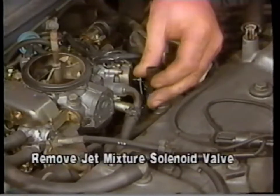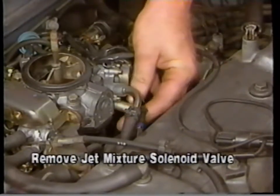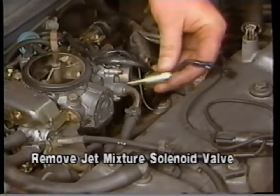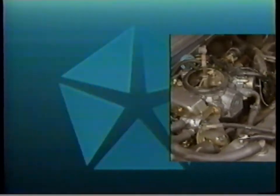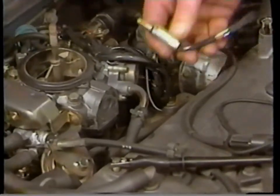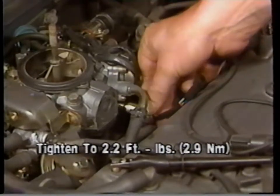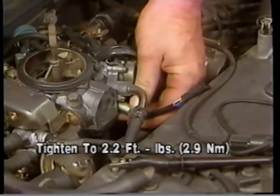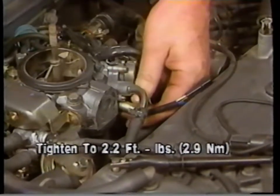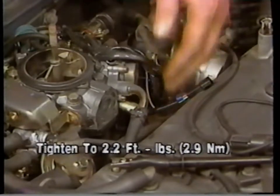To do this, disconnect the solenoid valve connector. Remove the jet mixture solenoid valve and set it aside for return to the warranty material return center. Install a new jet mixture solenoid valve and tighten the valve to 2.2 foot-pounds or 2.9 Newton meters. Be careful not to over-tighten the valve, since this will distort the valve and cause an over-rich condition.